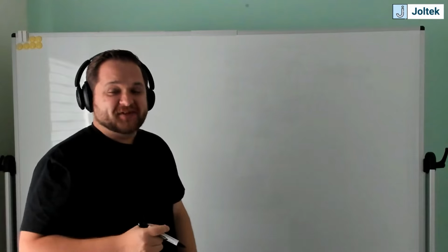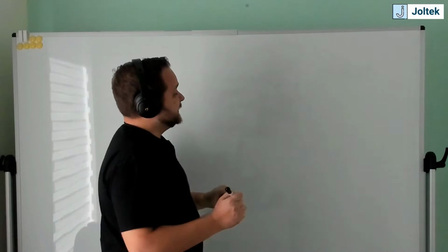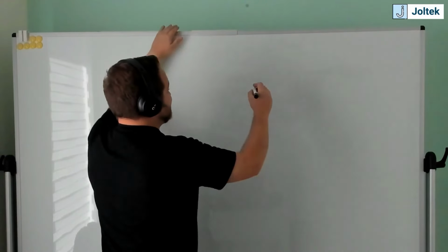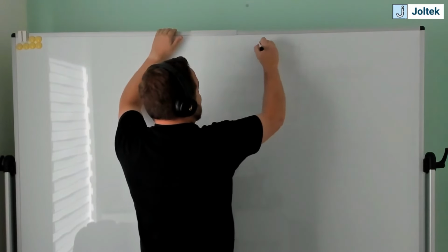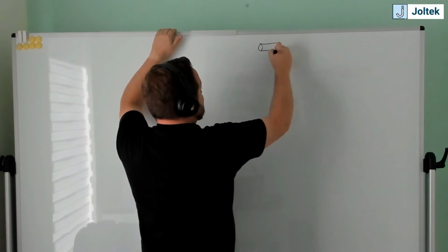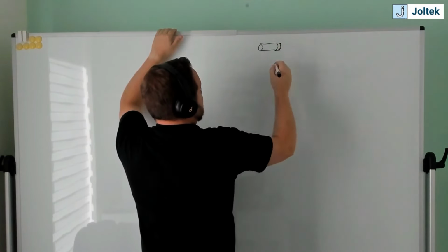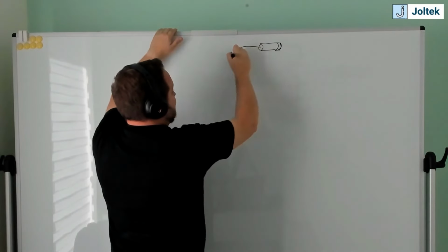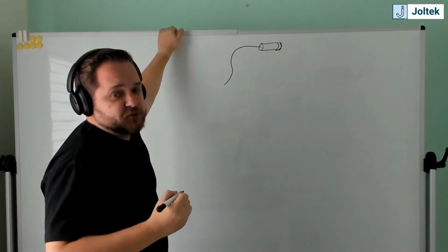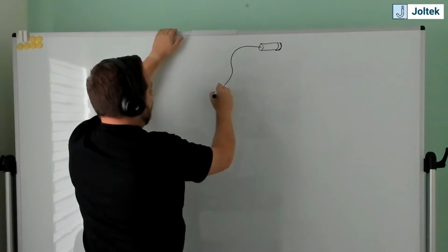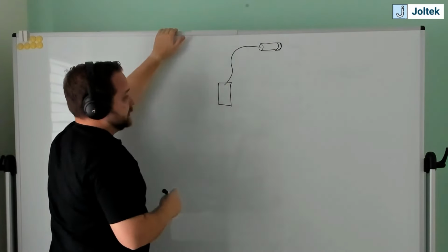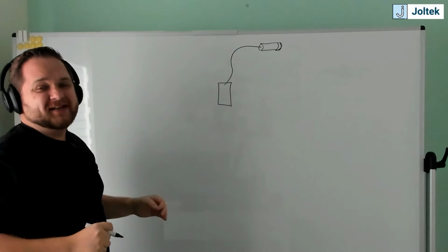And we're going to map this out as best as I can. So ultimately, let's look at a sensor. In this case, it's going to be an inductive prox, very simple. This is as basic as you can get on the production floor. So this sensor is going to have a wire that goes into the PLC as we've discussed before. And this is going to be a card. In this case, let's assume that the sensor is digital.